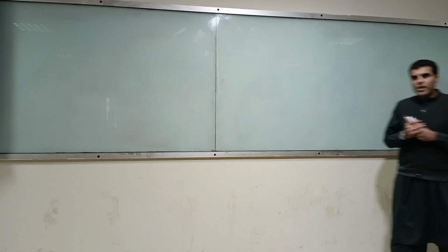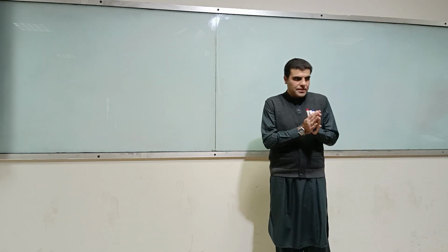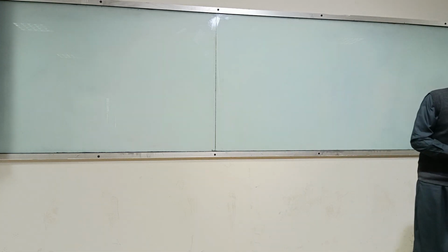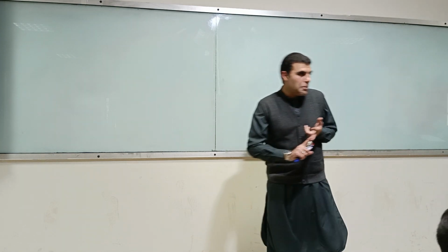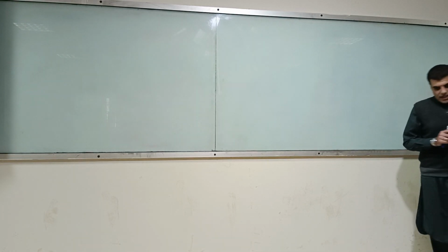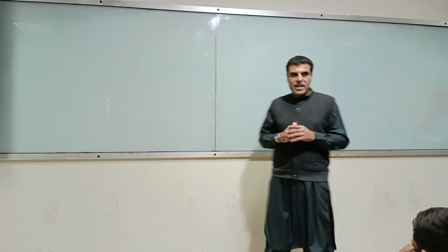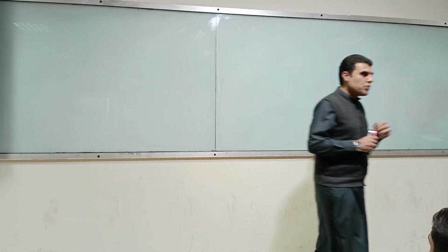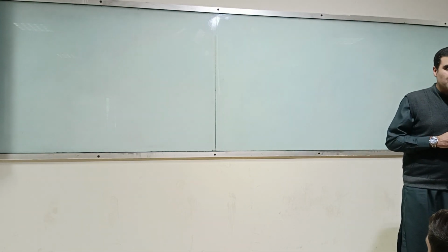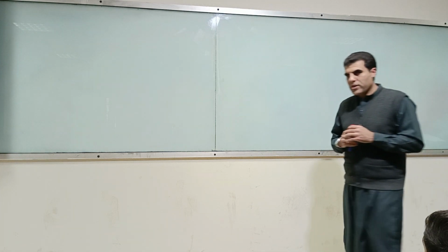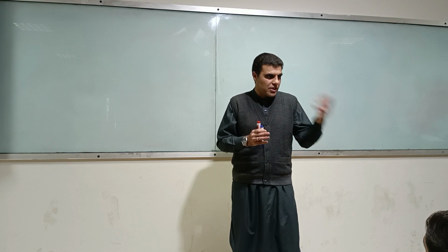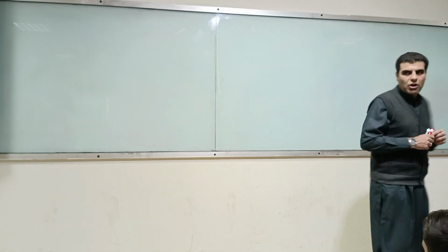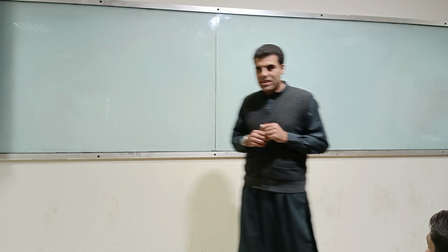The first starting point. Okay, can I have your attention please? Okay, so we discussed what determinate structures were, indeterminate structures, and then how stability is relevant to our determinacy and indeterminacy. Okay, the determinate structures, we said, are those structures in which you have got number of available equilibrium equations equal to number of unknowns. Okay, so number of available equations are the equilibrium equations, depending whether you have a 2D structure or a 3D structure.